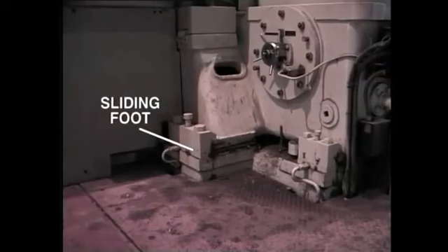After a short overnight shutdown, it is probable that the turbine's shell will still be considerably expanded, while the rotor has contracted to provide a negative differential. This indicates that a hot start is required. Please make sure to check the manufacturer's recommendation for your particular machine.